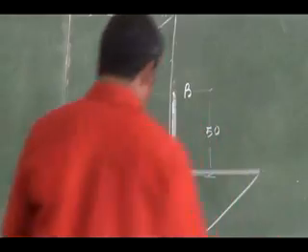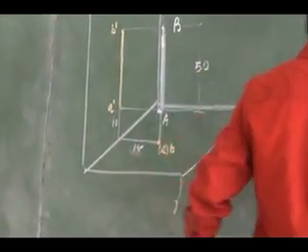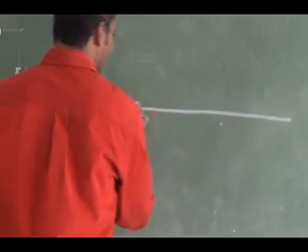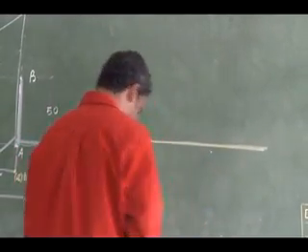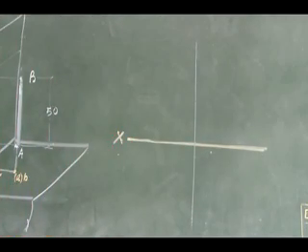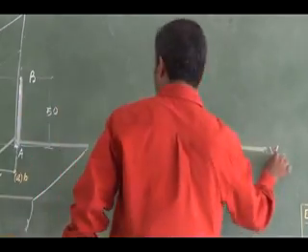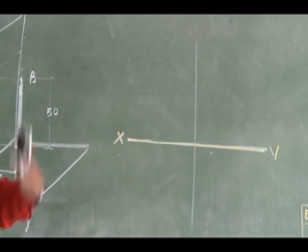Now I can rotate this horizontal plane 90° clockwise and I can draw it. So this is the one. Then I can draw a reference line. Right. So from the reference line I will have my front view. First of all, the end location is given. That end location, first of all, you can mark it.